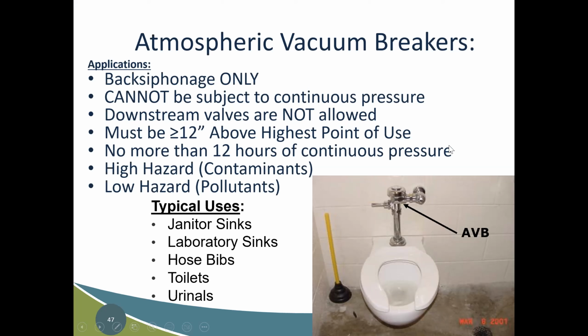There's another thing that's interesting about these. They're not supposed to be used for more than 12 hours of continuous pressure or use. And the reason for that is that block that we were talking about can become lodged in the top of that crown. So it's not to be used for high hazard application.